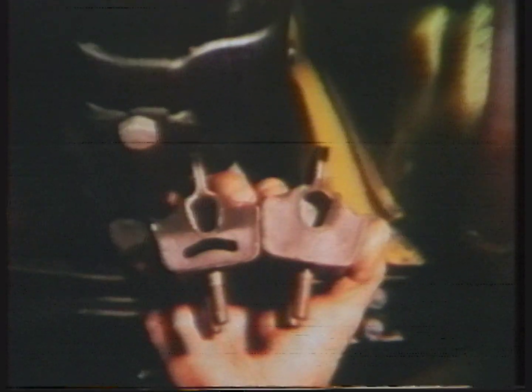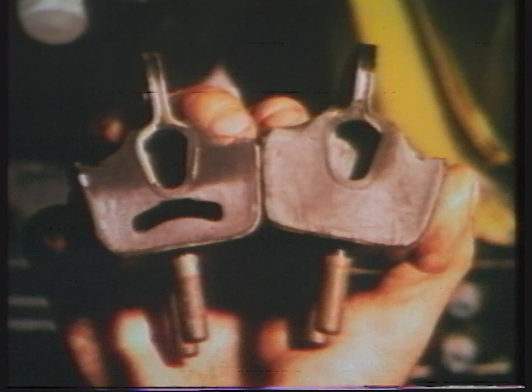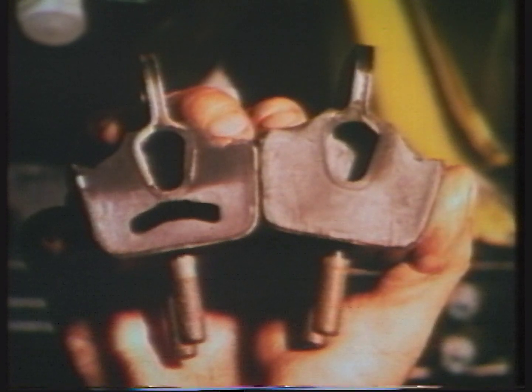Make an overall inspection of the steering and suspension for signs of damage and/or looseness of components, and rectify before balancing, as these may magnify an existing problem. Engine and front suspension mountings, torque loading and correct type and position of engine mounting rubbers are critical if vibration at the front occurs in the 45 to 55 miles per hour speed range.